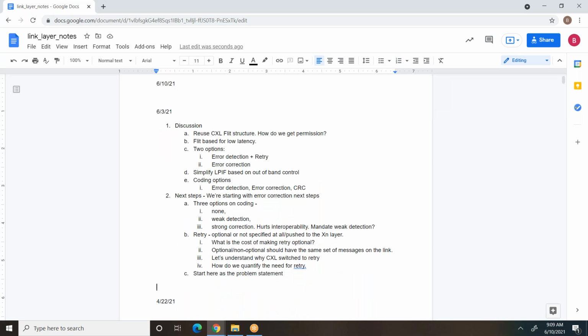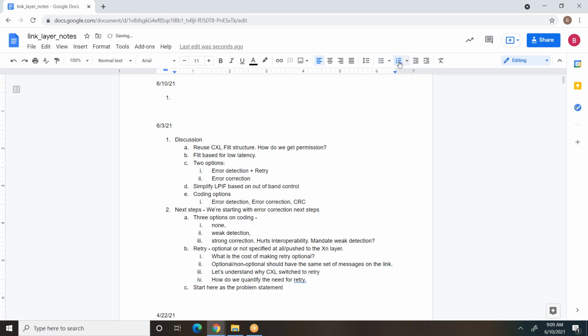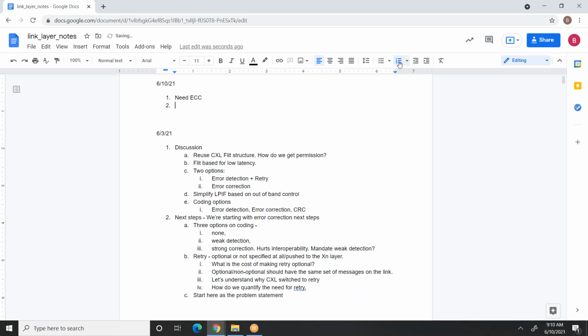I think the objective was to define a generic link layer that could be used with a variety of PHYs, and then do a worked example for BoW, and that would mean an extra sub layer, a lower link layer if you like, to define how you get from the generic link layer to the BoW service interface.